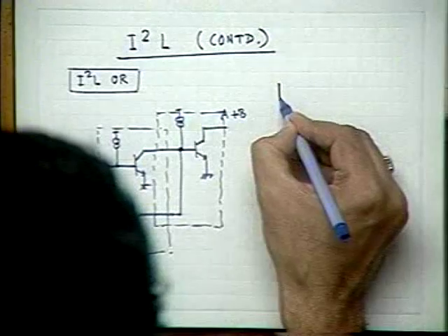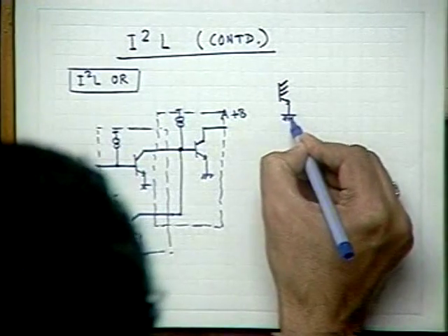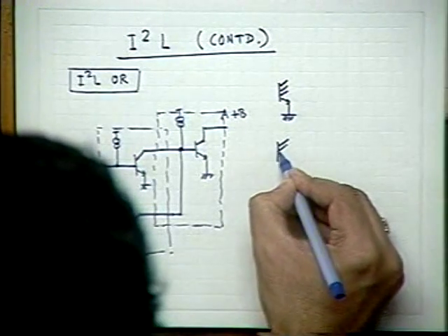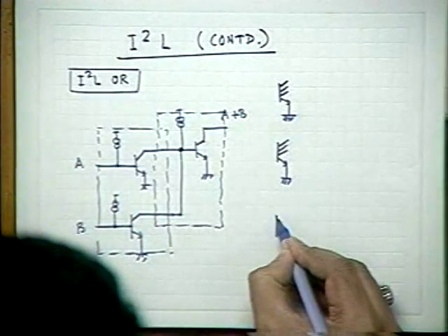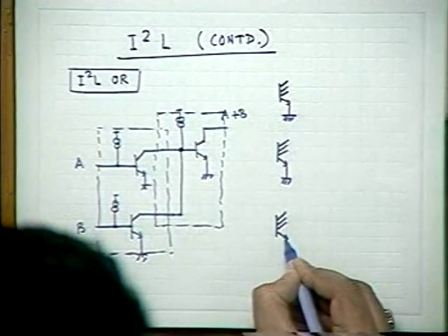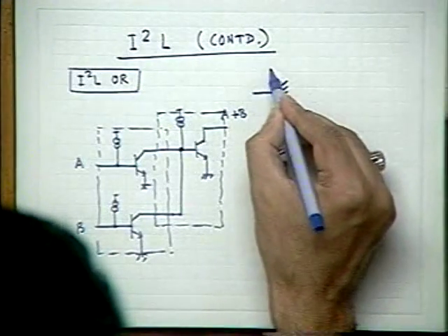Alternatively, you can think otherwise: you produce a NOR gate and then invert. So it is like this. And if you want to produce multiple functions, as in the previous case, again you have to make use of multi-collector transistors.